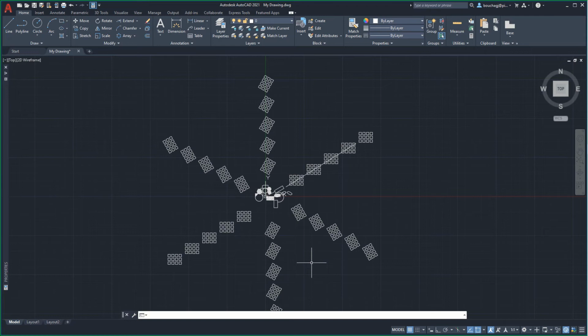Note that the default settings for Polar Array is a polar array of 6 items that revolve 360 degrees about the chosen center point. Again, within the squared brackets were several command options, and post-creation, there are many adjustments that could be made to this polar array in the Properties palette.